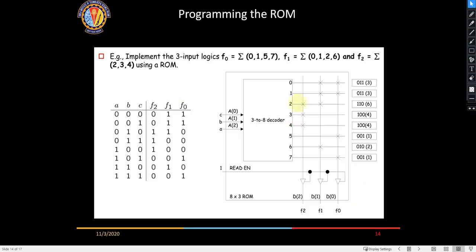So ROM can be used to save several data, say in 8-bit or 16-bit data, for given input address lines. That is one application. The second application is sometimes you want to program it for a fixed function. So these functions can be permanently programmed here like this. This also can be done here.